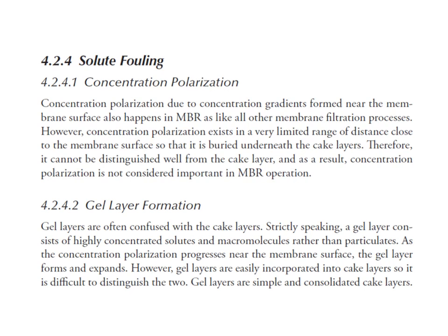In the MBR process, where cake formation normally happens, concentration polarization actually happens inside the cake layer, so it is not simple to distinguish the effect of concentration polarization from the data of cake formation. That's why people don't normally mention concentration polarization.